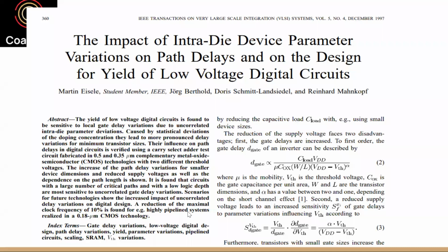And that's why we had that ratio of 2:1. That is again a very textbook thing. In the latest technology nodes, in FinFETs and so on, the number is very close to 1.1 or 1.05 or something like that. So it all depends on what kind of transistors you have, which technology. But yes, based on this mobility ratio and the relative drive capabilities, you have to size the circuit if you want to have balanced rise and fall times, is what I meant.